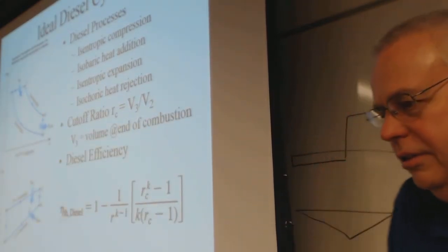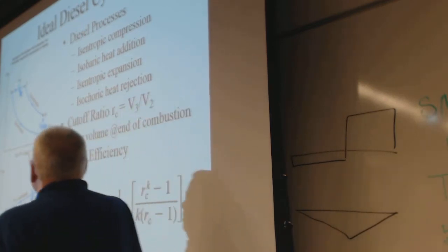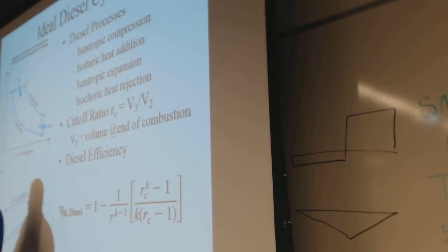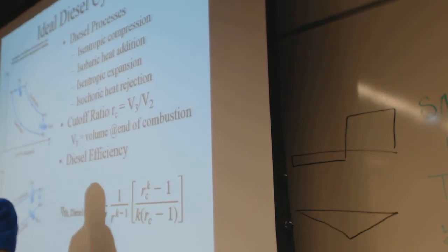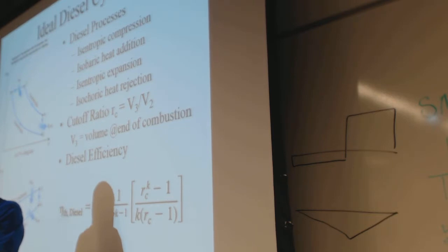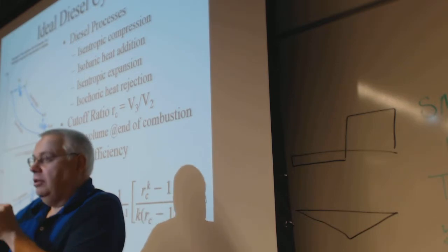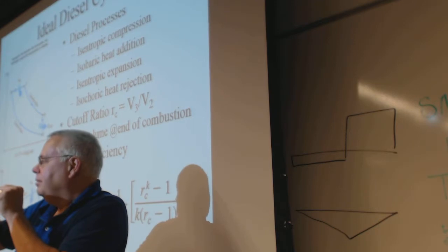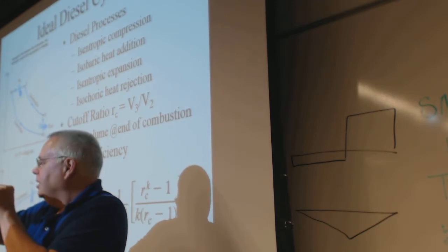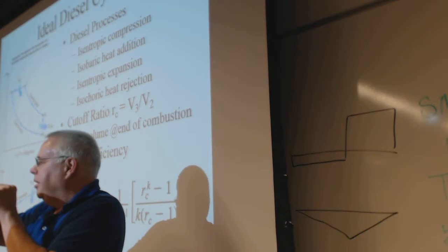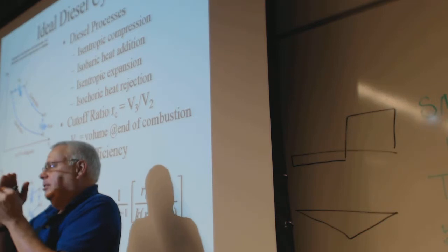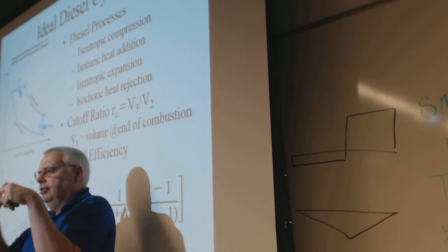So anyway, diesel cycle is the main difference. Instead of a constant volume heat addition, it's a constant pressure heat addition. The burn happens slow and it chases the piston, and if you inject the fuel at the right speed, then because there's an amount of time it takes to push all the fuel in there, it will essentially burn and maintain the pressure as the piston is moving, which normally, as the piston moves, pressure goes down, but as the fuel goes in, the temperature rises.